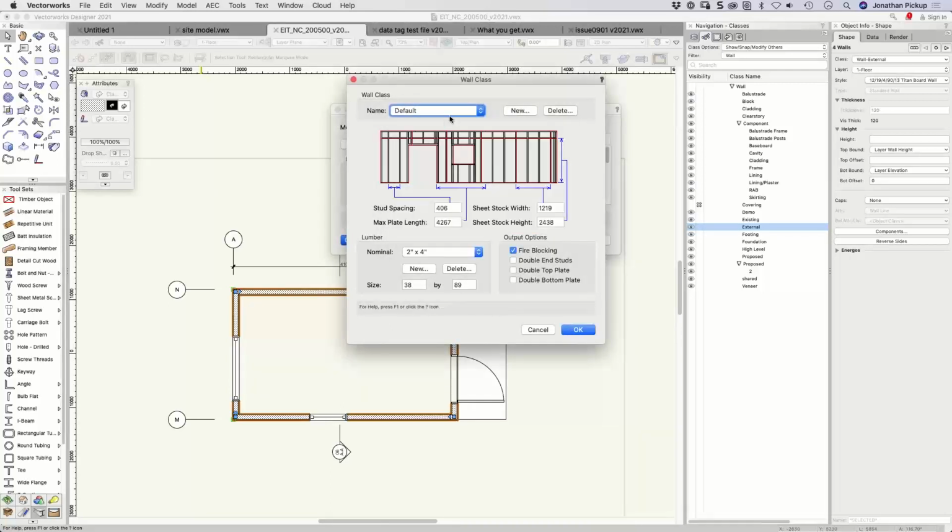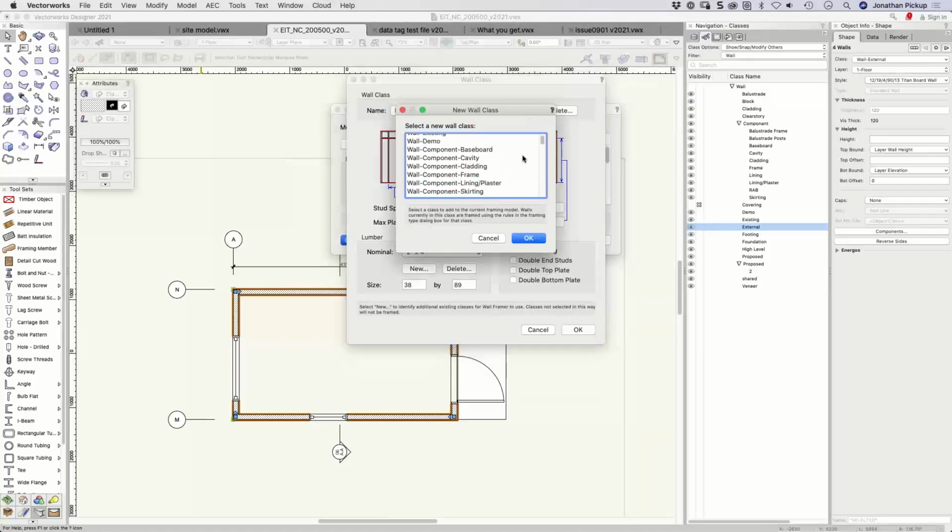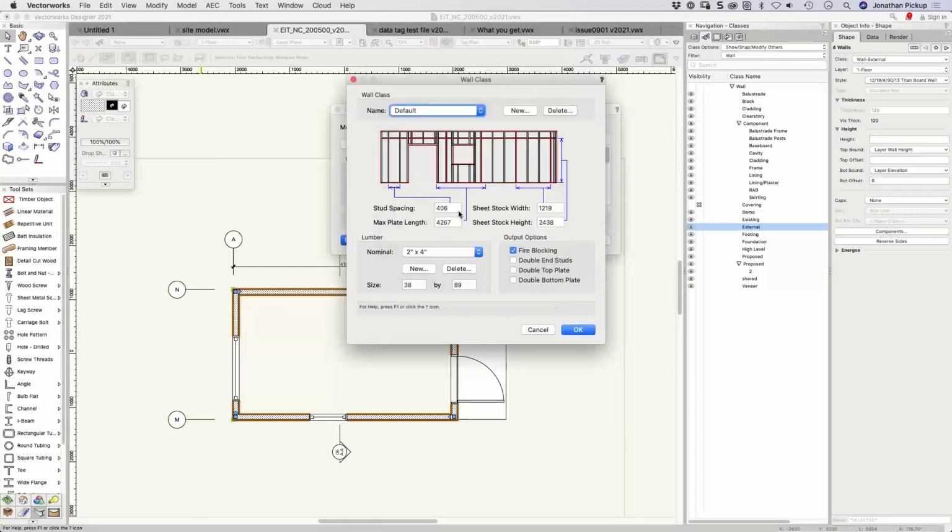No, it doesn't. It's already got it, I think. It says default there, but I can't choose the wall external, so it must know that it's already got wall external. Is it there, down the bottom? And they don't seem to be sorted alphabetically. Weird. Okay, so what's my stud spacing? 600mm centers. What's my plate length? Maybe 5 meters. This will then calculate how long it can go.